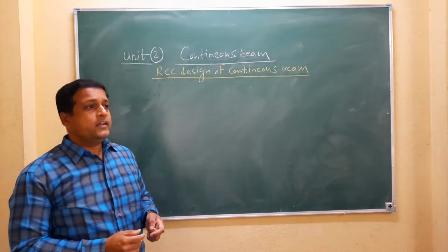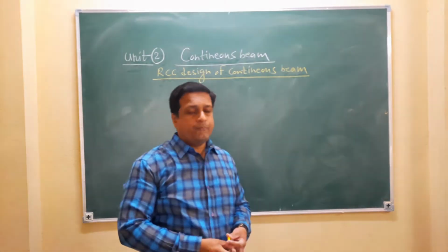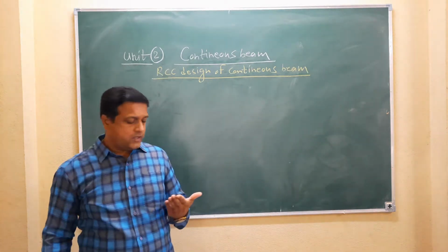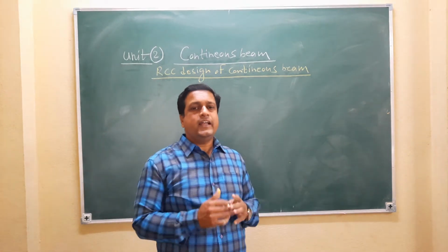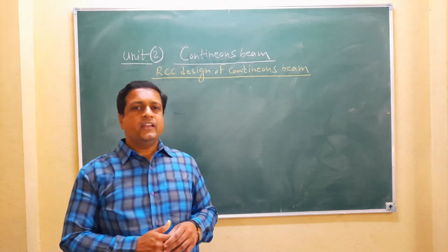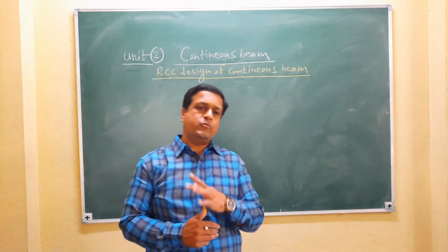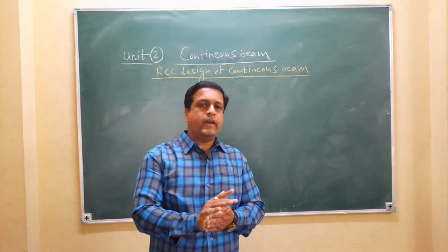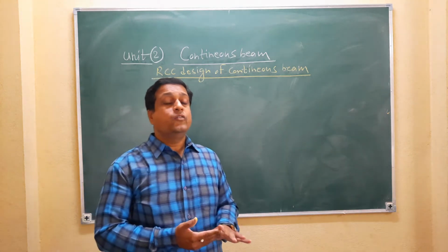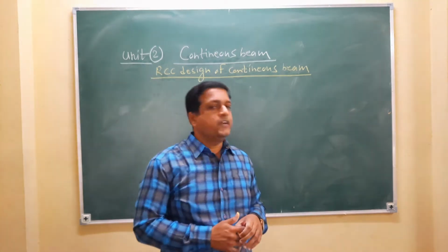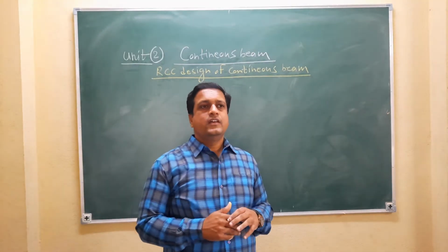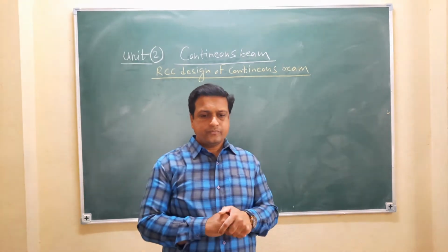Already I have told you what exactly the design of a beam is. Design of a beam is nothing but you have to decide the dimensions of the beam. You have to design the longitudinal reinforcement, the tension reinforcement at the bottom. You have to find the compression reinforcement at the top. And finally, the main thing, you have to design the shear reinforcement. That's it. If you have done all these things, the design of the beam is completed.